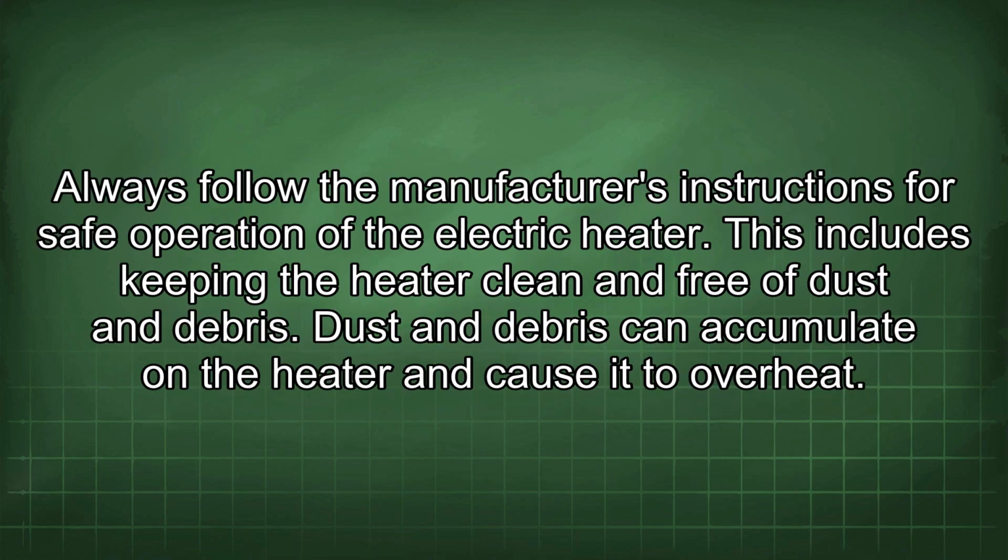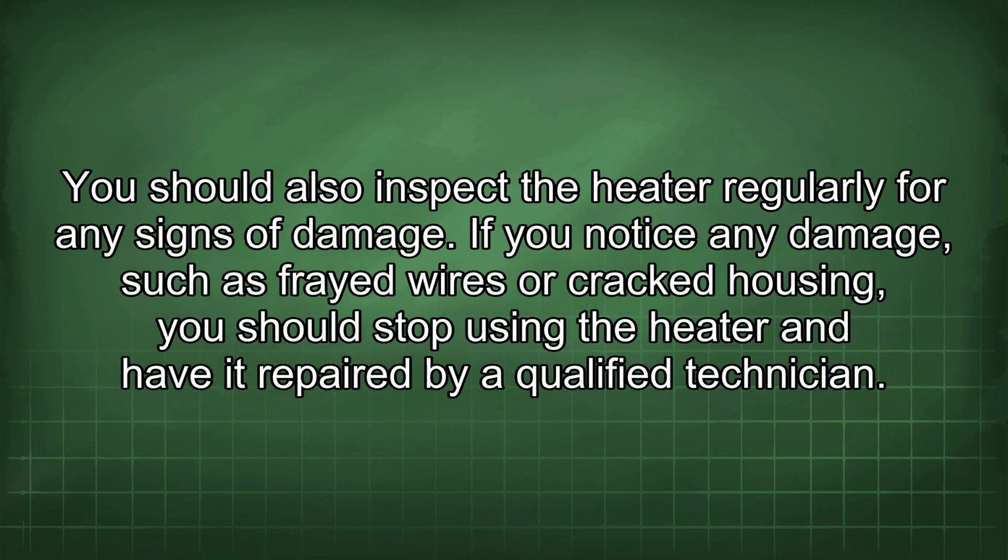Always follow the manufacturer's instructions for safe operation of the electric heater. This includes keeping the heater clean and free of dust and debris. Dust and debris can accumulate in the heater and cause it to overheat. You should also inspect the heater regularly for any signs of damage. If you notice any damage, such as frayed wires or cracked housing, you should stop using the heater and have it repaired by a qualified technician.